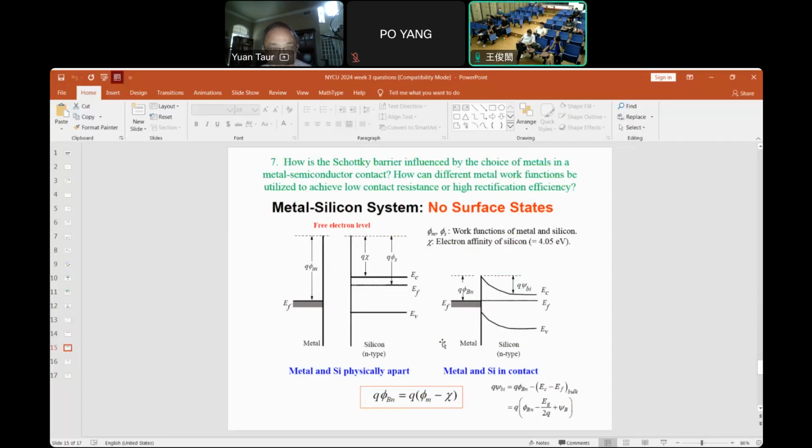Yeah, I think indeed for CMOS, you have N plus and P plus contacts that you have to worry about. So typically, try to choose the mid gap, or don't make it too asymmetric, to simplify the process steps. But then we have to use very, very heavy doping at the interface to get into the tunneling region so that we can get lower contact resistance.